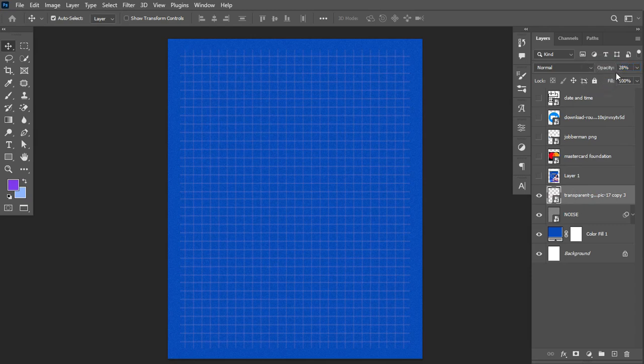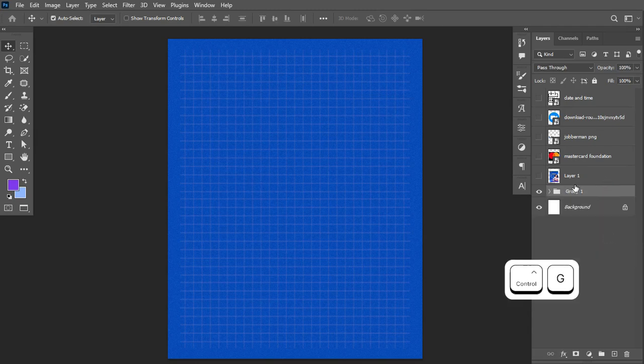Okay, this is actually okay. Around this is okay. Okay, that is in terms of this. So moving on, I can select this layer by clicking on this, holding Shift, click on this, hit Ctrl+G to group, and I can choose to rename this to BG, which basically stands for the background. That is in terms of this first thing.